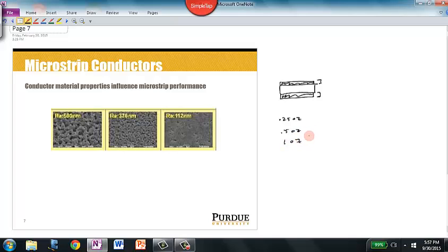So what are they saying? Deposition weight, what this means, 0.25 ounce, means that they've applied 0.25 ounces of copper evenly per square foot of surface area. So they've taken by weight a 1/4 ounce of copper, and they've spread it perfectly flat, or as flat as they can, over 1 square foot of the substrate material. So what that translates to, for fixed metals, is a common thickness. So for example, 1 ounce is 1.4 mil.